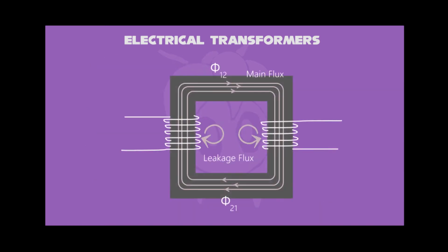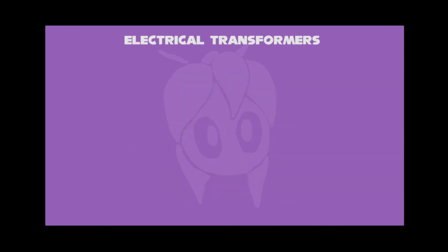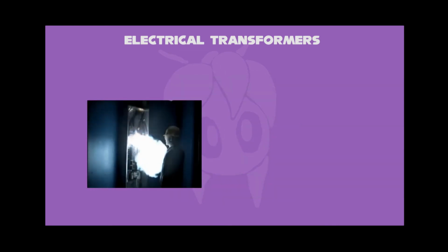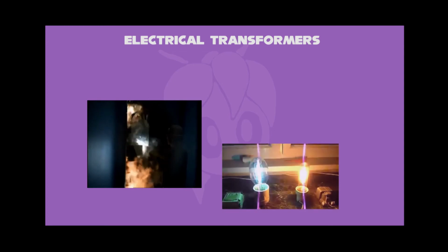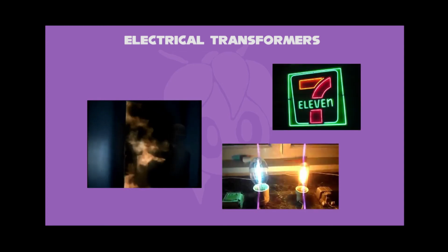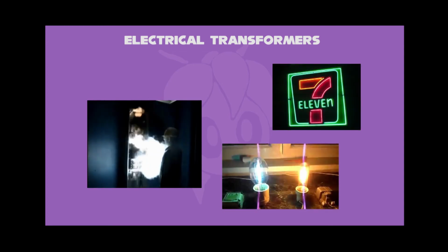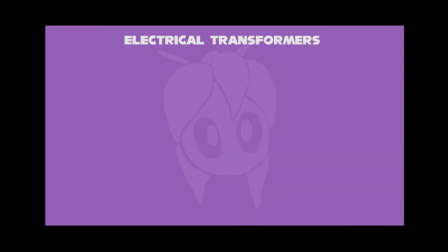In this diagram, inside the magnetic core, there is a leakage flux which, generated by the primary winding, links all the turns of every winding, including itself. Leaky transformers may be used to supply loads that exhibit negative resistance, such as electric arcs, mercury and sodium vapor lamps and neon signs, or for safely handling loads that become periodically short-circuited, such as electric arc welders.